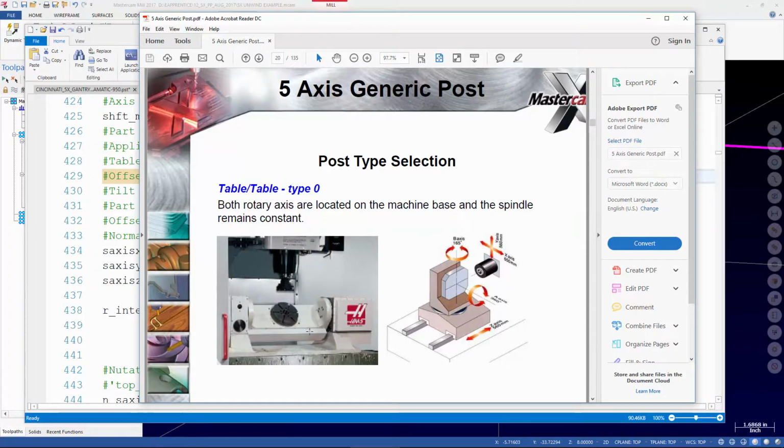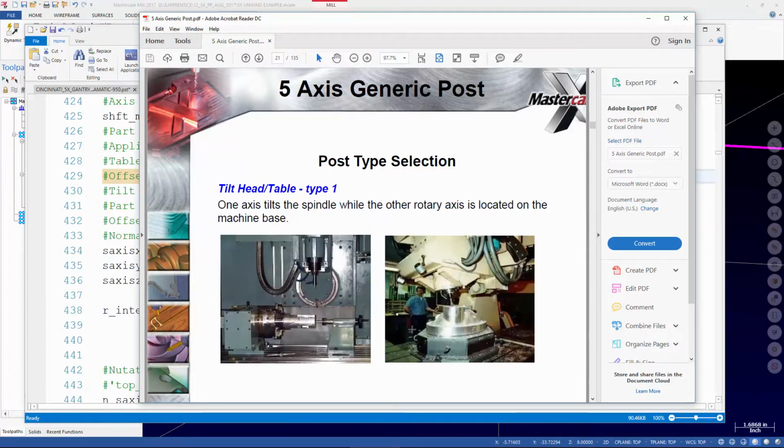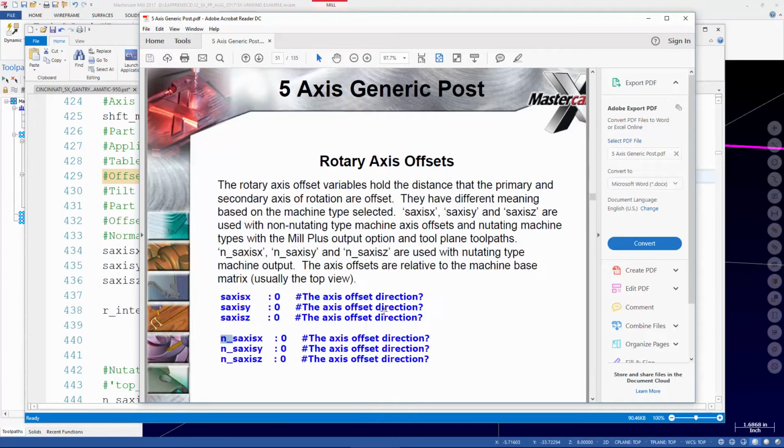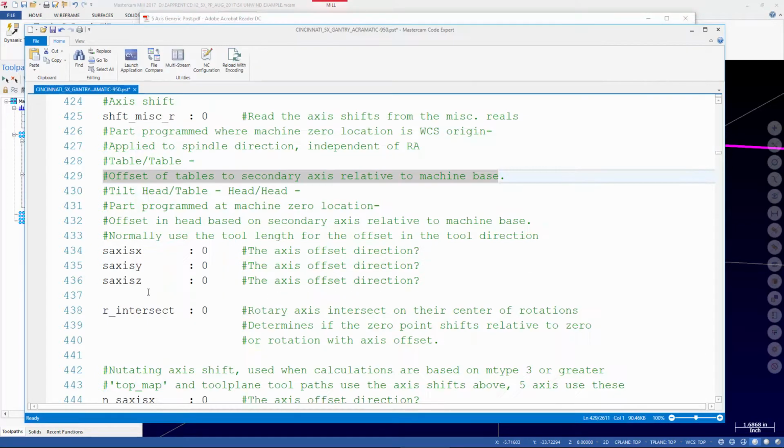And in addition, there will typically be a slight offset in Y. So, you know, they don't build these things exactly perfect. In some cases it can be up to a thousandth, but usually it's about 3 to 6 tenths plus or minus in terms of how these things rotate relative to each other on the machine. And so what this allows us to do in the post is input those numbers and allow the machine to compensate.